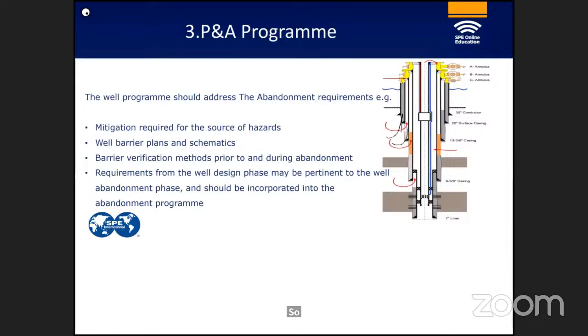Well barrier plans and schematics need to be created. Barrier verification methods prior to and during abandonment have to be documented and implemented at the execution stage. Requirements from the well design phase may be pertinent to the well abandonment phase and should be incorporated into the abandonment program.